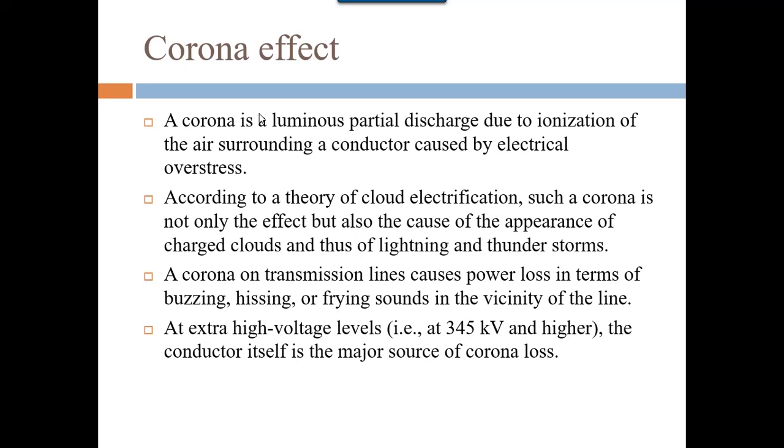According to a theory of cloud electrification, corona is not only the effect but also the cause of the appearance of the charge of the cloud, thus of the lightning and thunderstorm. So when charged clouds strike each other, then the light or the lightning which appears, according to a theory, is also called a corona effect. A corona on a transmission line causes power losses in terms of buzzing sound. So we can hear some buzzing or hissing sound or some frying sound in the vicinity of the line.